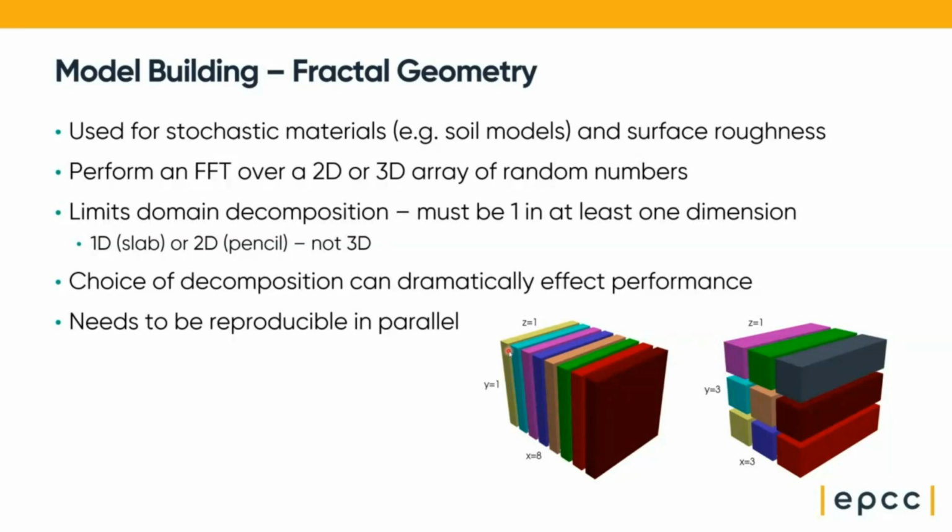Because the fractal geometry takes more processing, your other 4 ranks which aren't processing it are just waiting, and you've got a load balancing problem. But if you just rotate your decomposition such that it's covering maybe this half of the model instead, you've got all 8 doing a little bit of it. So that's one occasion where how you decompose your domain does matter a fair bit.